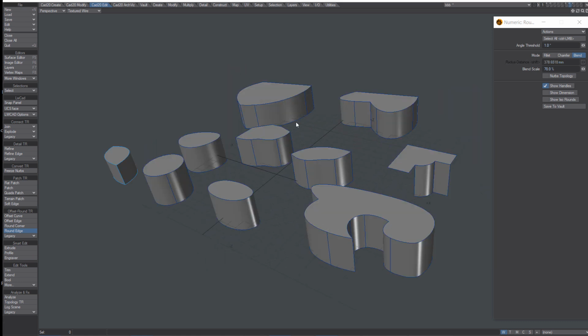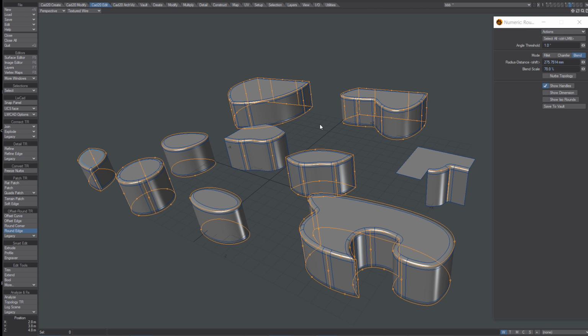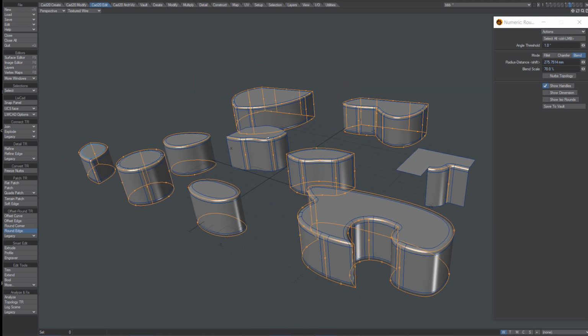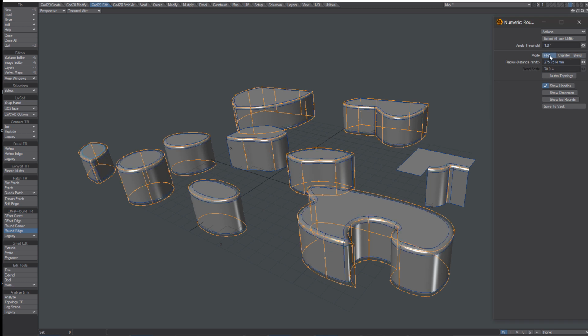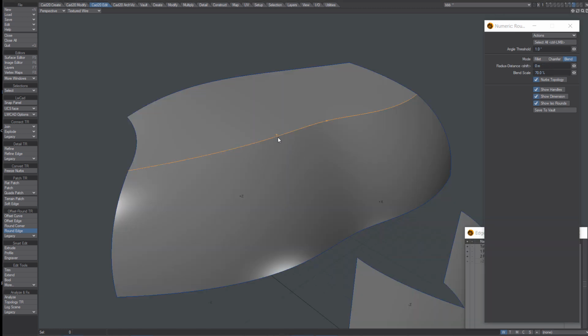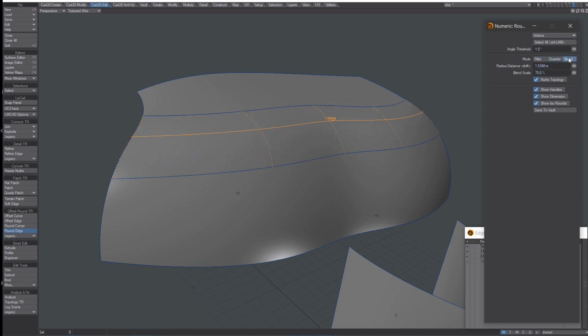It works also 100% on objects which are mixed with polygons, flat surfaces and NURBS surfaces with no more than 2 incident surfaces per edge. So for these mixed surfaces or objects, it works 100%, same as the polygonal version. Here on this object, a lot of cases were resolved, and now it works very well. And finally, we have cases when both sides of the edge are NURBS surfaces. The previous version of the round tool was almost useless. Now it works very well because there is a new design.